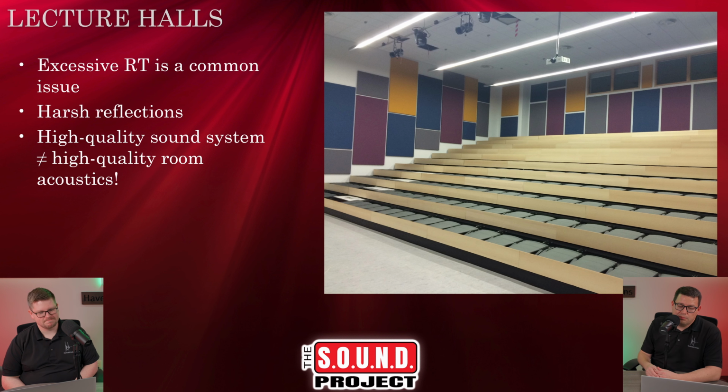Lecture halls are another place. It's like a classroom, but a little bit bigger, and reverb time plays a bigger factor. With the excessive reverb time that happens in these spaces, we have to be even more careful with what type of acoustical materials are used and where they get placed. A lot of times these lecture halls have a little bit better sound systems than the standard classroom would, because some small classrooms don't have a sound system and the teacher projects their voice. In lecture halls, sometimes you need some added PA, so that can introduce some challenges into the room.